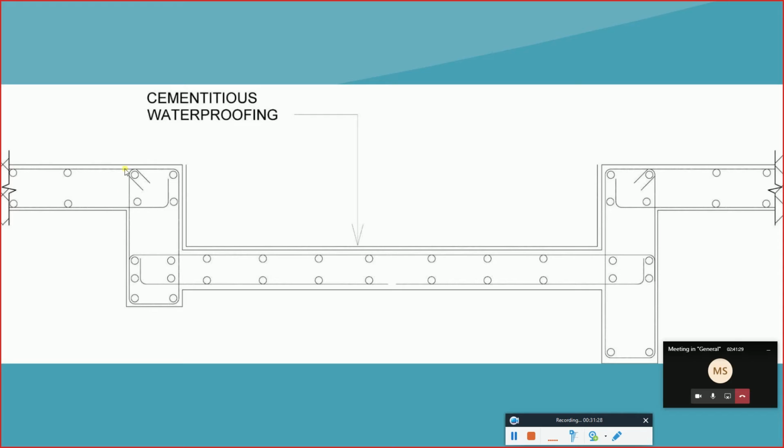Okay, and this is how it looks like. We either supply a rectangular beam here supporting both the slabs, the regular slab and the sunken slab, or we have a Z beam like whatever we have shown earlier in terms of beams. Again, of course, you need to provide waterproofing, since water connection is happening a lot here, and you don't want your reinforcement to be disturbed. Mainly in Oman, we use a rectangular section rather than a Z section for the beams here.